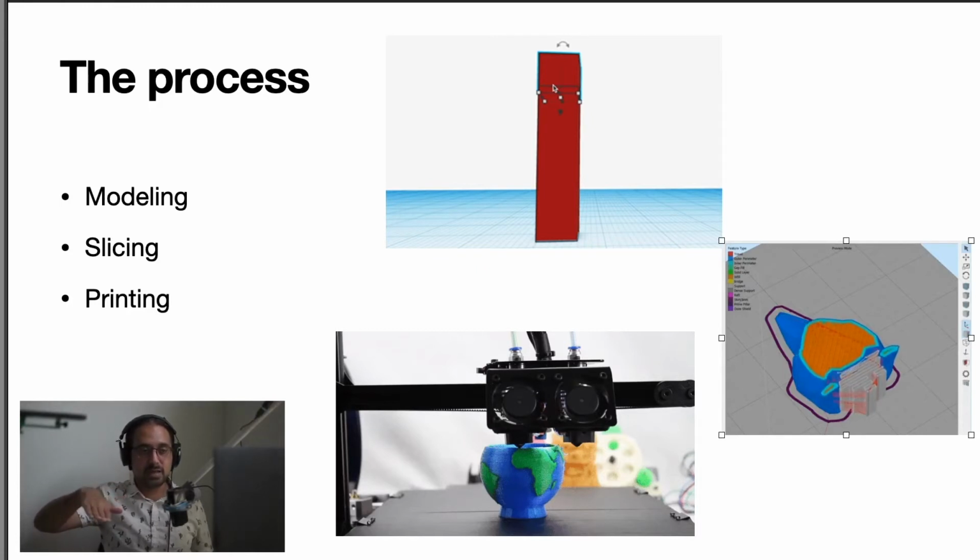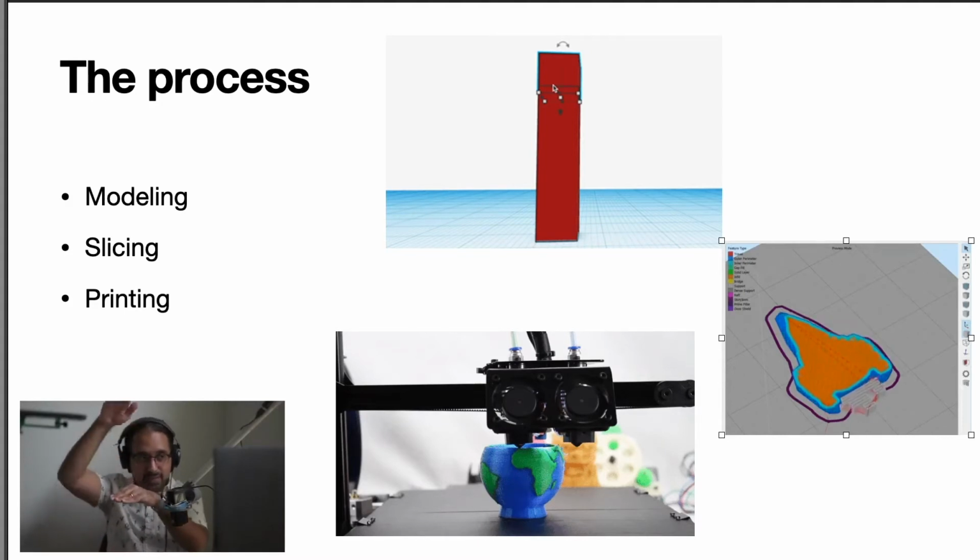So a lot of this is based on precision. It's based on strength. These different types of patterns and different percentages of what's called infill will give you different model properties. But the slicing step itself used to be a lot more complicated, but nowadays it's fairly straightforward, and we'll talk about supports and rafts and what happens at the bottom of the model in a future class. But I'll just leave that abstracted away for now. The important thing to remember is that the model is generated from the base of the plate and then built up in layers on top of that.